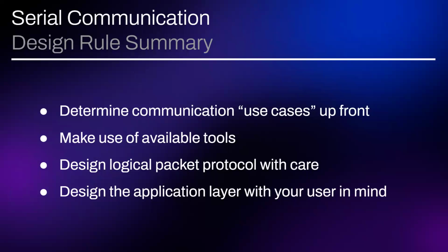How about you? I use it a little bit at a high level. I'm building an application layer on top of a CAN RFID scanner. In order to flash firmware onto the scanner, they have a serial adapter, but it's not like an RS-232. I needed to buy a specific cable and then wire it into a serial adapter, and then the serial adapter needed to wire into my USB. It was a whole daisy chain. It's like, just let me plug in a USB.